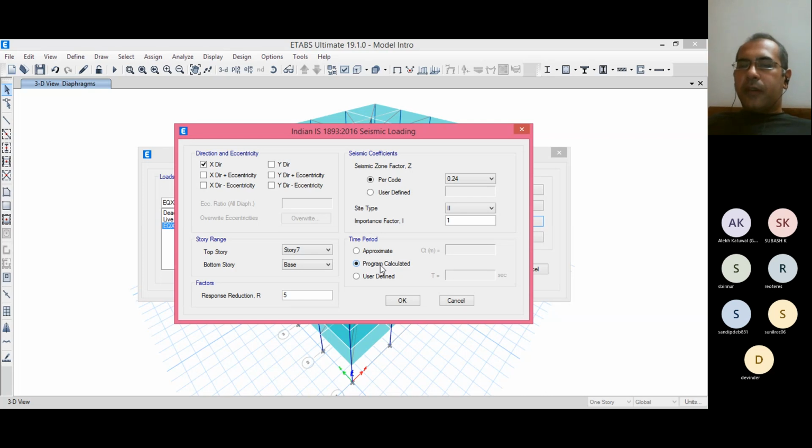So if you are doing the response spectrum method, in which the dynamic analysis is done, it may or may not be accurate, because in dynamic analysis we are generally not considering the infills, and many other things. So the stiffness of many portions of the building is not considered in our matrix when we are generating the matrix. We are neglecting that.